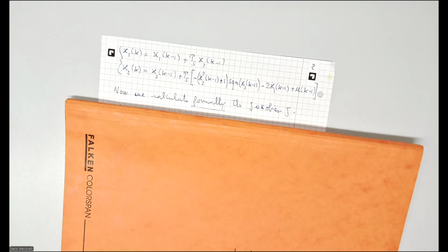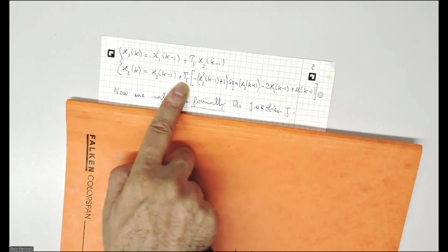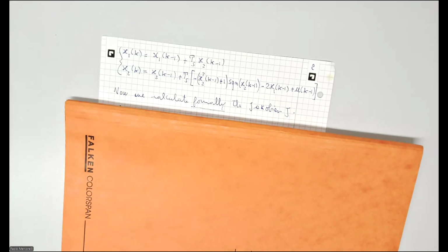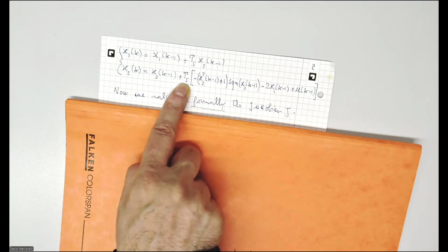We can do it, but we have to do some approximation or method in this implicit form. It is a little bit complicated. This is the price which we have to pay. The advantage is inside the structure of backward, or the implicit, which typically is more stable, but we need an explicit form to be implemented in Kalman. More stable typically means we can use a little bit larger, I would like to say, sample time. And this technically is useful because the Kalman filter, as the control system, runs within the sample time.